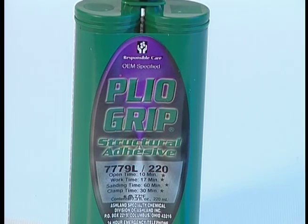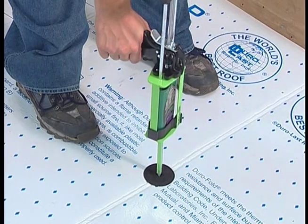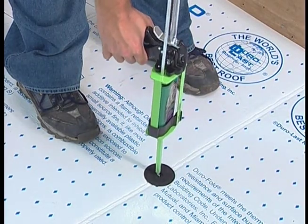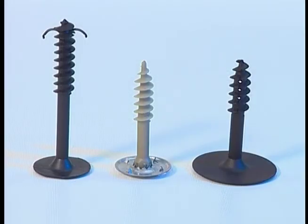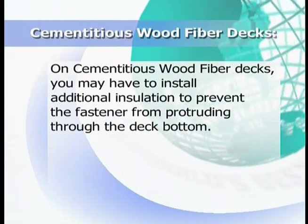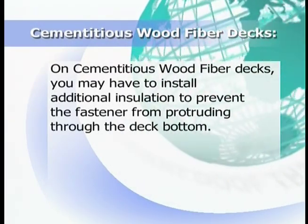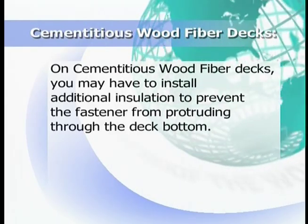With liquid auger fasteners, you can increase pull-out resistance by adding a 2-part epoxy into the fastener, as shown. The shortest NTB is 2.5 inches. The shortest auger fastener is 2 inches. And the shortest liquid auger fastener is 3 inches. On cementitious wood fiber decks, you may have to install additional insulation to prevent the fastener from protruding through the